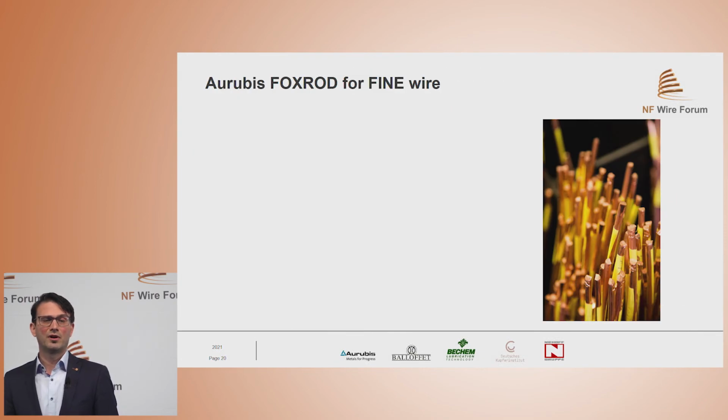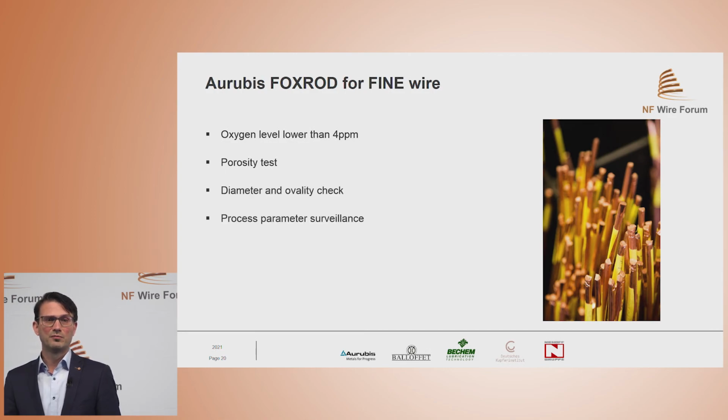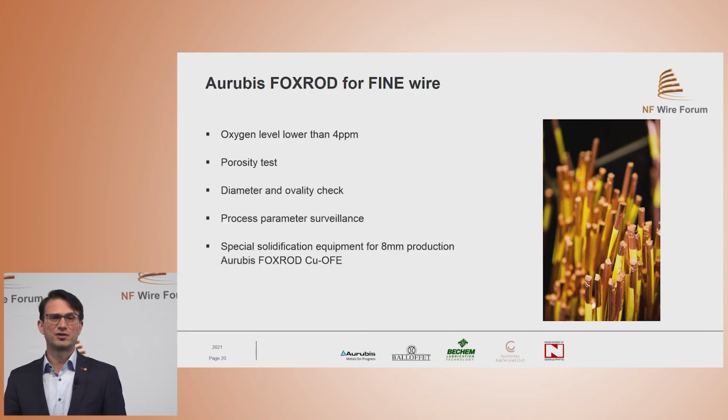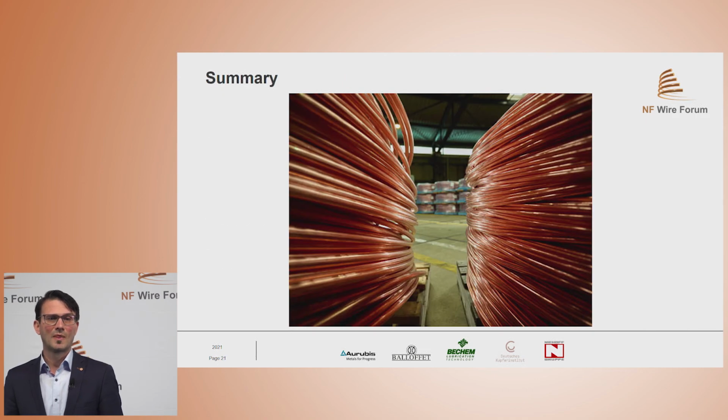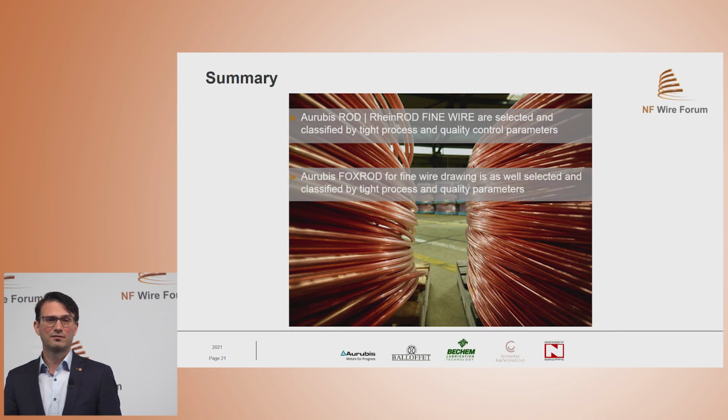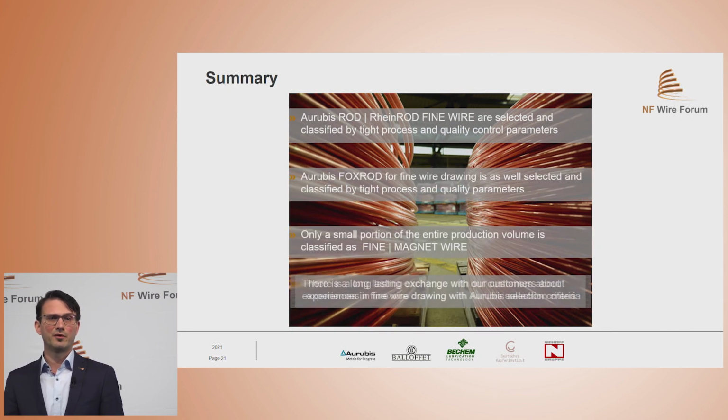To draw copper oxygen-free rod, so-called Aurubis Fox rod, to small diameters, some points have to be taken into consideration. Process parameters, special solidification equipment, and application of graphite crucibles are important to produce Fox rod with low porosity and no inorganic inclusions.